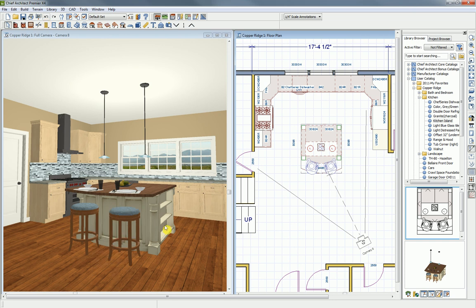Okay. So we can change the color configuration slightly and move things around on our kitchen island. Now, I kind of like this distressed paint color that we have on our island, so why don't we add that into the rest of our design? We'll activate our 3D and get into our eyedropper tool. We'll pull up this pink color. And we have a couple of ways that we can apply a material. So at the bottom here we have a component, an object, a room, a floor, and a plan mode.